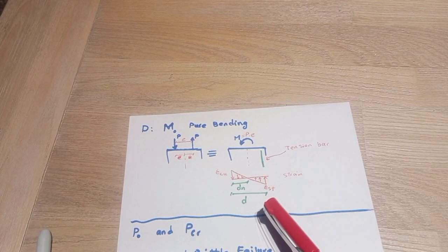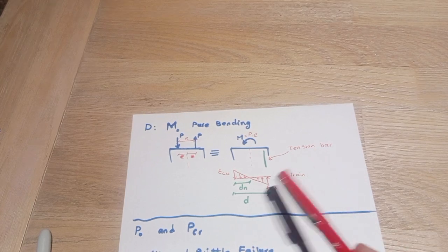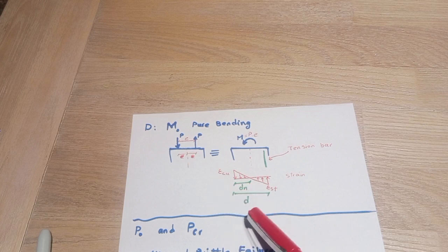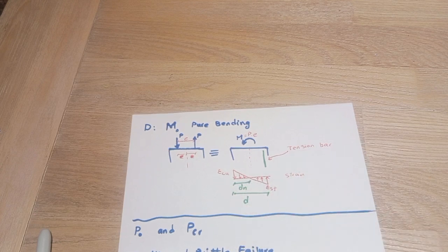So you know how to calculate this bending capacity. We will have D, Dn, and we have strain distribution that is always linear. We can assume that the strain is yielded, and we can go to check Dn and the M value, then we can do another back calculation to check if our assumption is correct or not, and it is easy to find this M value.